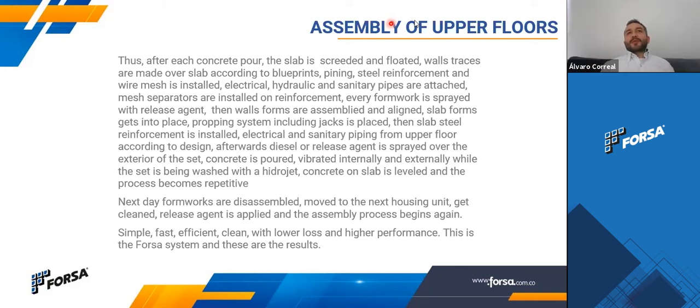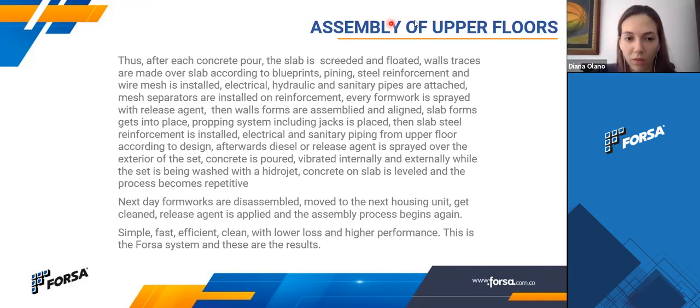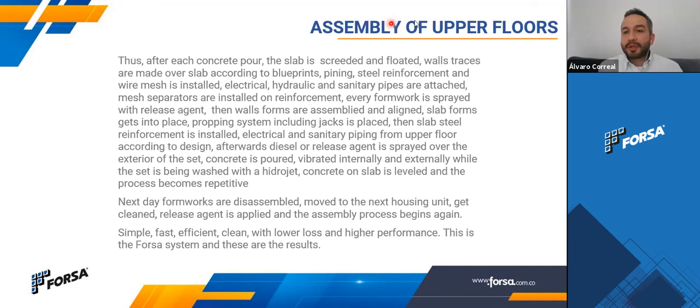Okay, that's why I said that it depends on the concrete design that you have. Most of the time, at the third day, you have achieved like 70% of the design resistance. So if you have 50%, of course you cannot strike these forms. That's why some of our clients are requiring 7 days, and we can provide these underpinning slabs and the back propping required for 7 days.